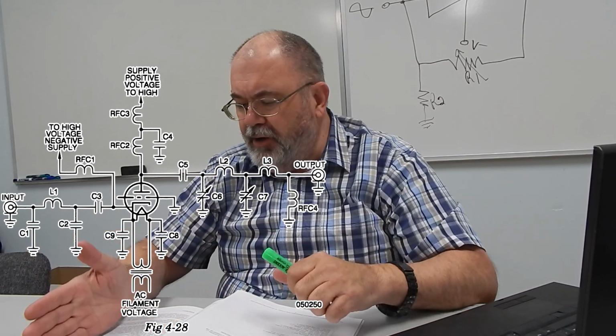Well, ignore everything to the right of it. Just go back and think, if it's a really low frequency like DC, is it going to go through? Yeah. If it's a really high frequency like gigahertz, is it going to go through? No. The capacitors are going to sewer it right to ground and the coil is going to say no. So it is a low pass filter.